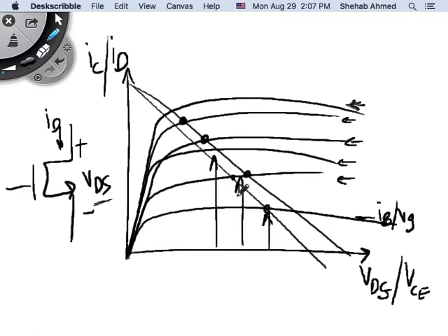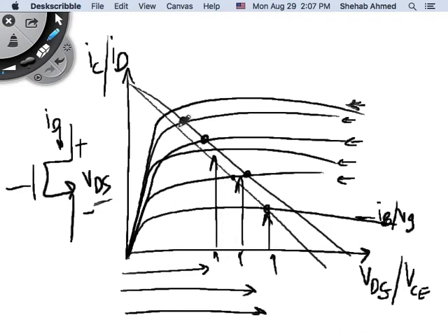So what does this mean? It means that I can have any voltage that I would like across a device. This is voltage across the device. I can make my operating point anywhere around here, correct? By proper choice of DC operating point, I can make a certain voltage drop across my device. And that's how you create a linear regulator.